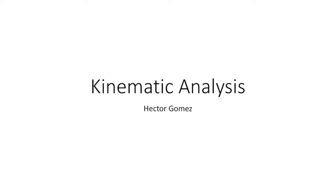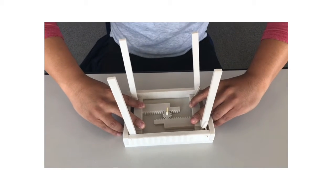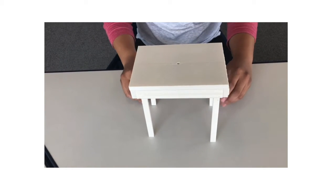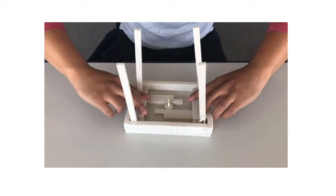Kinematic analysis. The kinematic analysis for the portable table requires that the table legs make a 90-degree angle when fully deployed and the coupler link to have a 45-degree angle to give the table legs enough support to be sufficiently rigid to resist collapsing into its folding position.